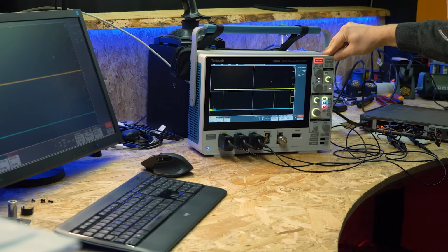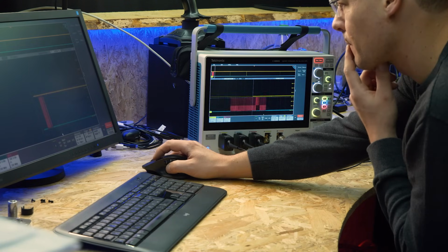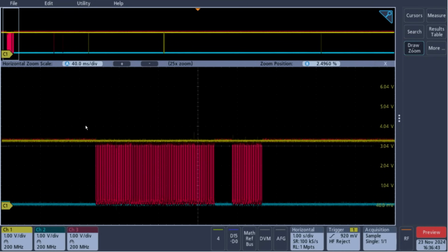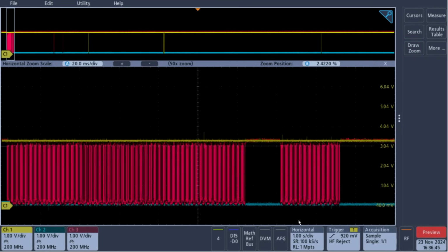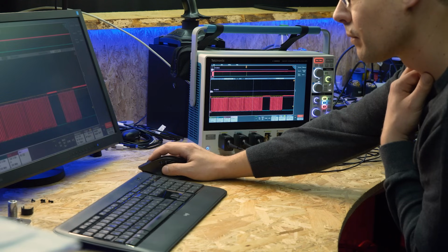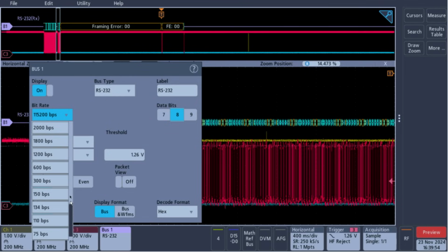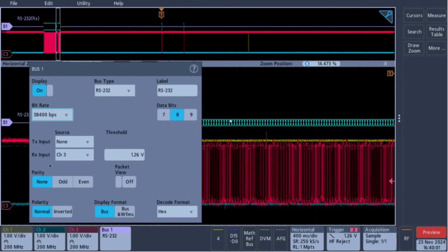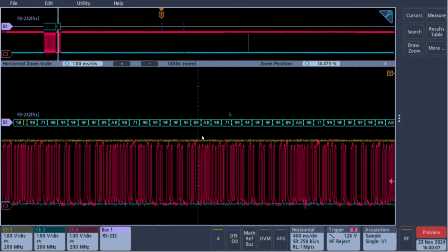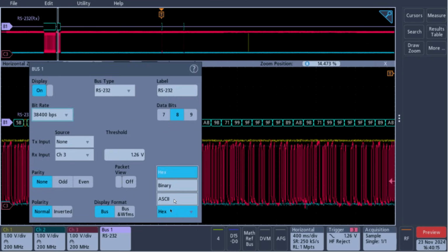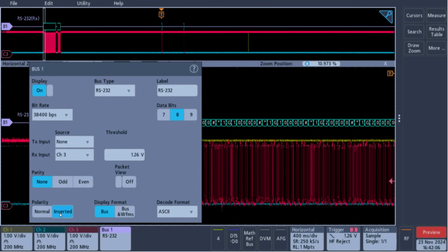So I started with classic UART and looked at the supposed RX and TX lines to the STM32. These are the resistors R59 and R102 on the X-Live. I then tried out the bitrate and coding for RS232 in the scope and changed some settings. And indeed, at 38.4 kilobaud, I was able to find meaningful hex codes that also correspond to readable ASCII characters.